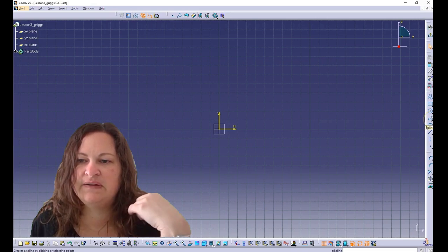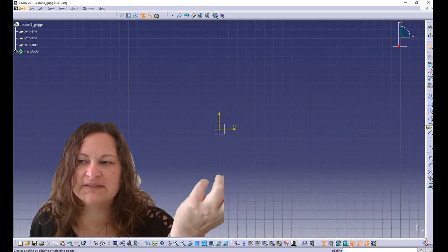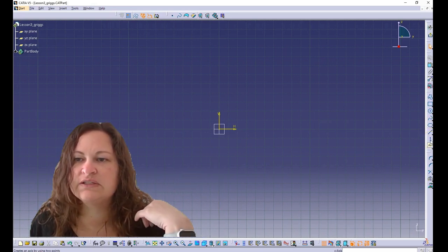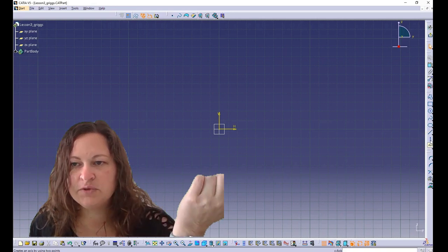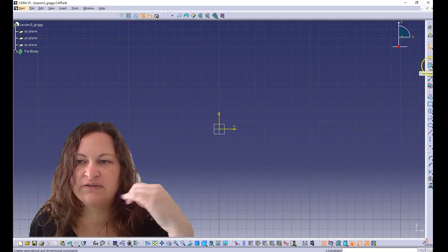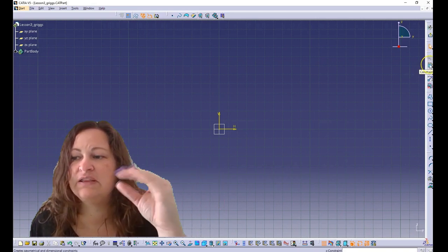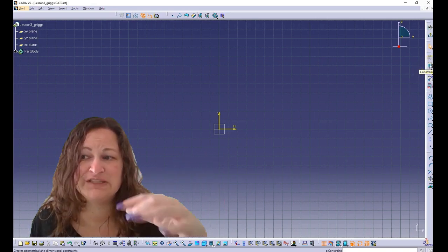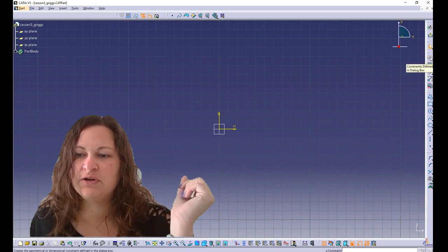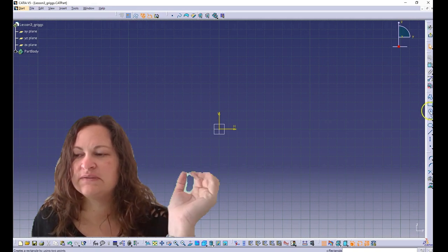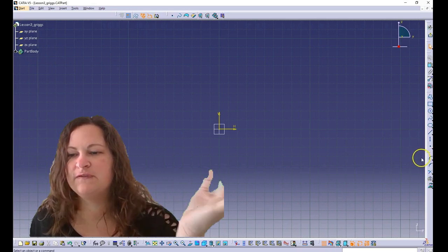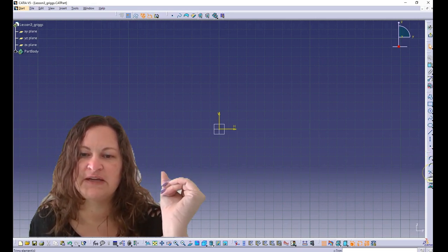And then you have reference geometry like an axis that you can add and helps you with some of your constraint generation, which is done using the constraints toolbar. You've got the dimensional constraints are just underneath the icon that says constraints, but anything that is geometric is going to be under your constraints defined in the dialog box. You also have an operations toolbar, which helps you make some modifications to your parts, curved edges, and it helps you trim off some lines, make some reflective symmetry objects, things of that nature.